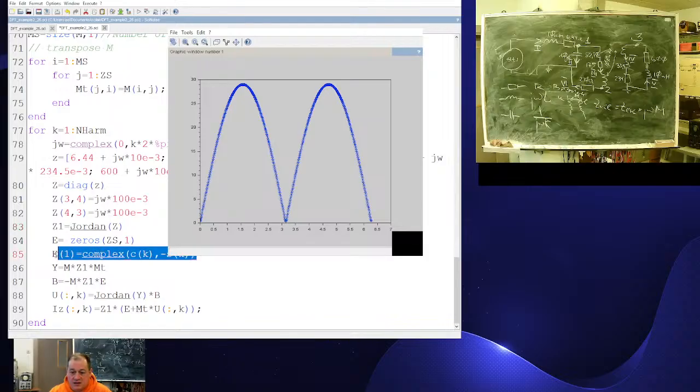Look at this. EMF, vector of EMF, I need to put EMF somewhere. I will use a vector for branches. Here in my network, I have only one EMF. It's my rectifier substituted with Fourier series. So EMF is an element of my Fourier composition. I'm solving very simply, through inversion of the nodal admittance matrix.